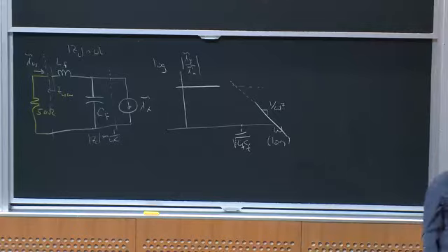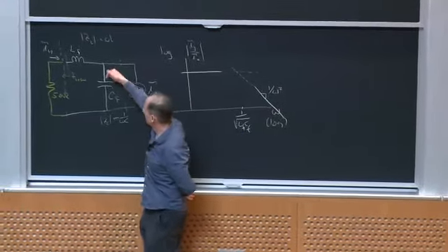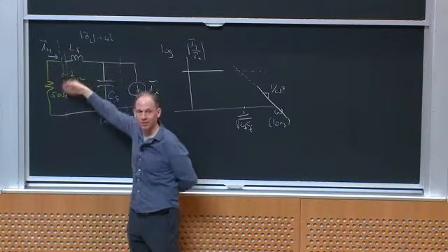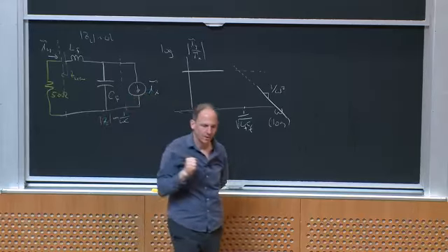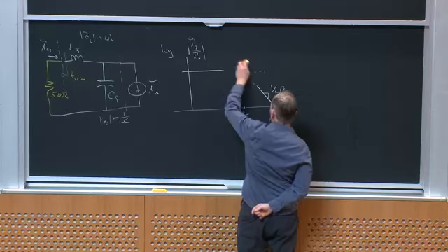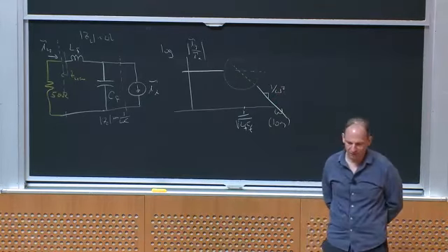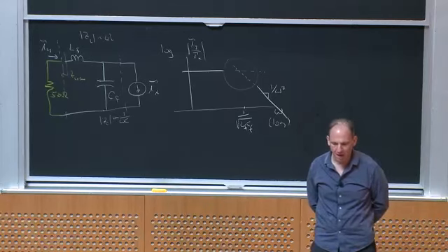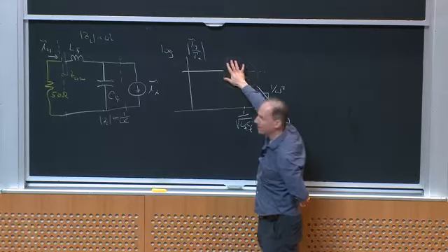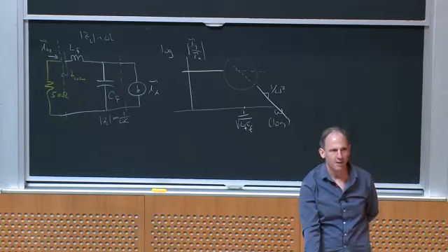So the way you might want to think about this is your filter's working because of the mismatch between the shunt path and the series path, okay? And if I don't like this, I can build higher order filters and so forth, and we'll talk about that. I haven't said what happens in the vicinity of cutoff. That's an important thing, and we're going to have to think about that. But let's, for the moment, not worry about what's going on here. We'll come back to that point, okay? So any questions up to now?